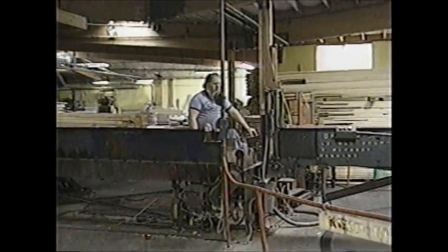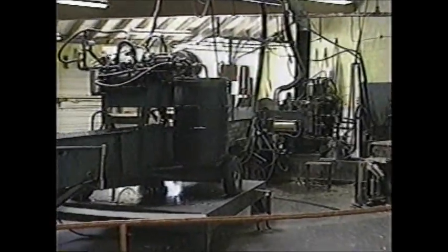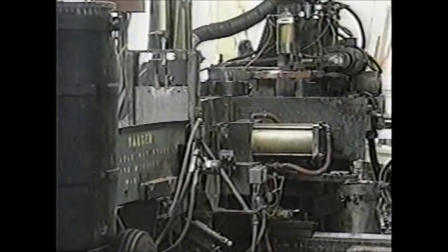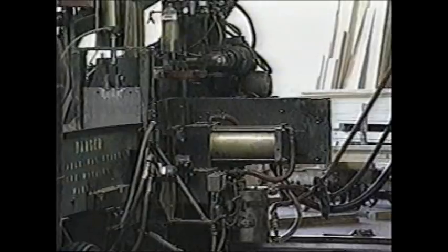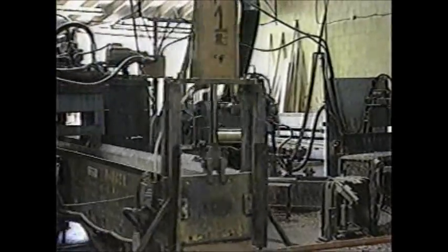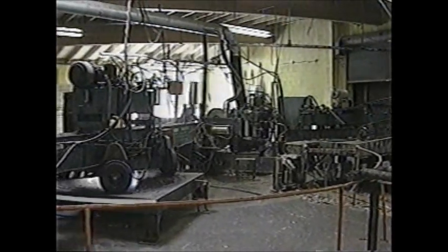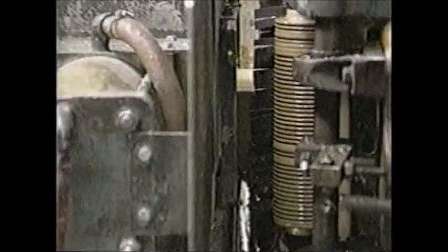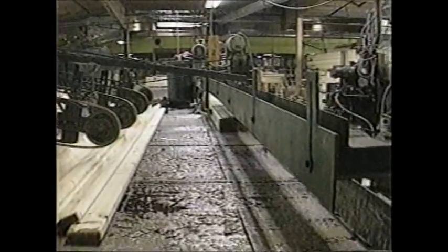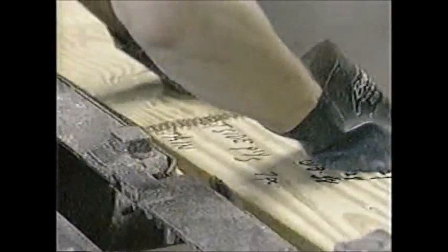The graded lumber enters production by first having finger joints machined in both ends. Due to the trimming of defects, lumber is random length. The finger jointing machine advances the lumber first to one end of the carrier, then to the other to permit finger jointing of both ends of the lumber. Glue is applied and the lumber is discharged to a conveyor. Finger joints are extremely strong and are used to produce a continuous length of lumber which will be cut into specific lengths according to production needs.